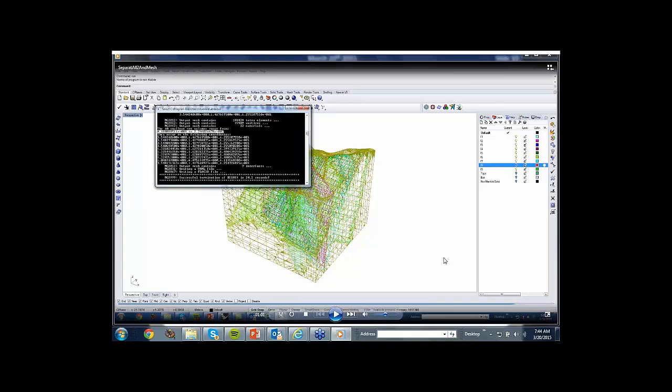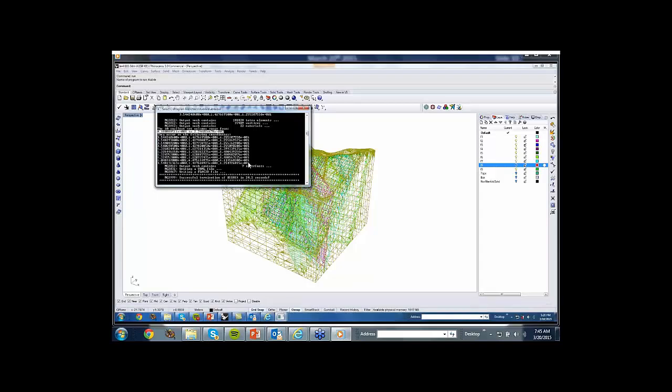So a little work, again copying and pasting these XYZ coordinates into Rhino after typing the points command will bring up those points, and then you can zoom in exactly in that area and see, oh my God, I have an element there that is the result of a fault coming very, very close to a surface, and that is creating a very small element or a bad element, which is going to later on cost me in terms of CPU time. So let's merge these two nodes together.